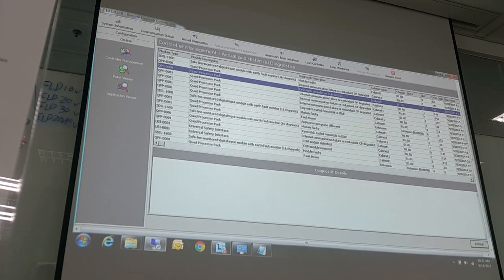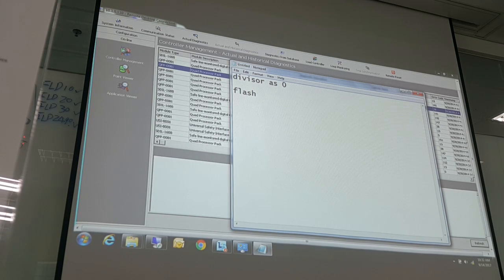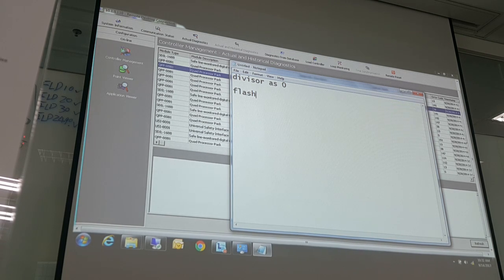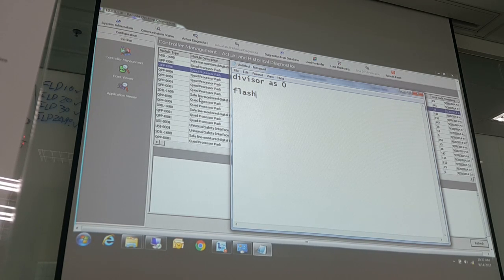Flash. Do you know flash? This is not like the C300. All the applications in the C300 run in what? Run in the RAM, right? So when you download the configuration in PKS, all the applications and configuration are stored in the RAM, and after you power off the C300, it will be lost. You need to checkpoint and restore, right?